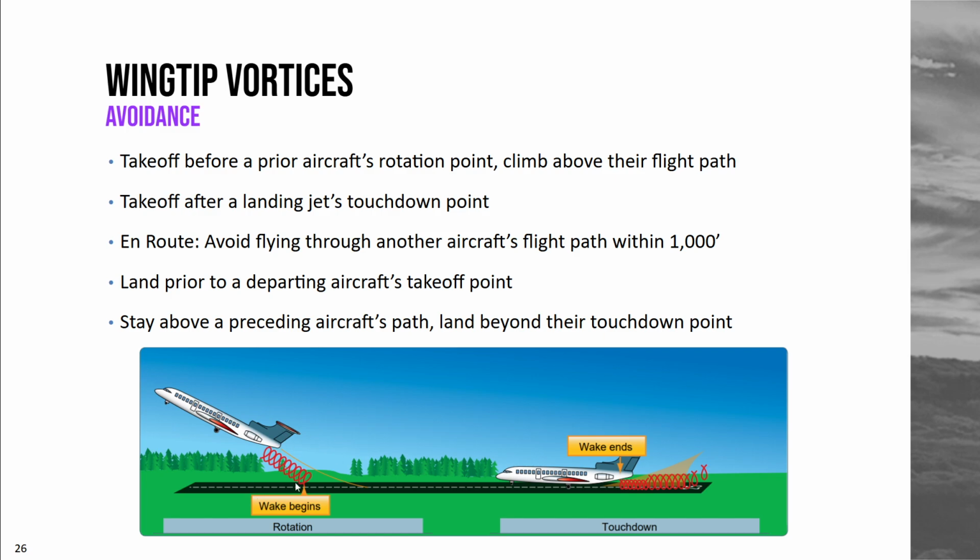Because these vortices will drastically reduce the lift of your wing, or even just one side of your wing, one wing and not the other, depending on how you hit this wake turbulence, which is extremely dangerous. So huge lesson learned there. It was one of those moments where I finally saw the practicality of learning about wingtip vortices go from classroom to real life.